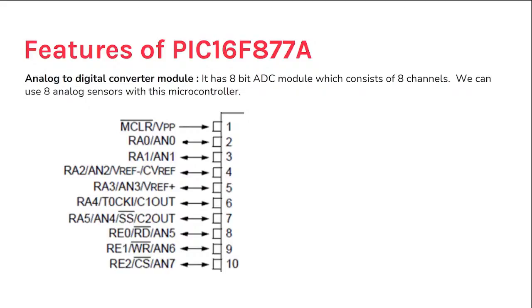The LPC4088 is a quad flat package which needs a soldering station to mount. So the best option is to choose the PIC16F877A series, which is also available in DIP package. For a beginner who wants an on-chip ADC, the best option is to choose the PIC microcontroller.